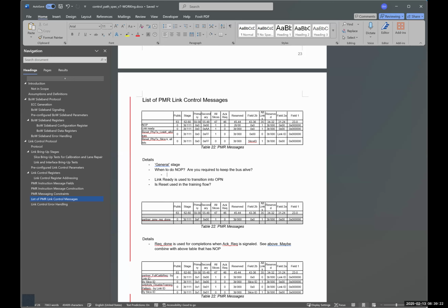I'm a little confused on what you mean by interrupting local software to take action. When you write a message into the PMR, shouldn't the implementation notify software there's a message? Right, you could do it that way too. A write to the PMR, you can detect that a PMR got written, and use that indication to also send an interrupt.